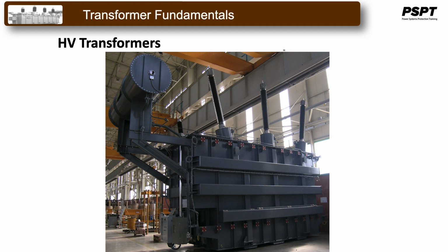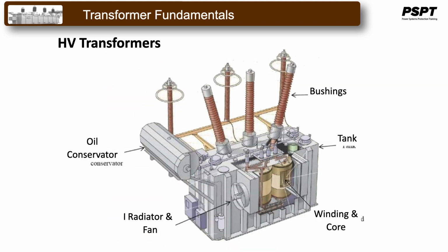Transformers are a critical and expensive component of the power system. Due to long lead times for repair and replacement of transformers, a major goal of transformer protection is limiting the damage to the faulted transformer. Some protection functions, such as overexcitation protection and temperature-based protection, may aid this goal by identifying operating conditions that may cause transformer failure. The comprehensive transformer protection provided by multiple function protection relays is appropriate for critical transformers in all applications.